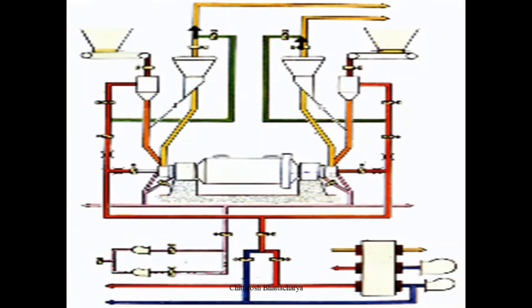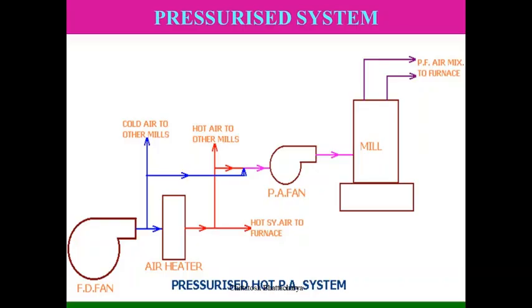We also have some bypass air supply to the classifier zone, and this air supply facilitates the classification process and helps in maintaining the pressure within the total flow line. So this way we have an arrangement of primary air supply at different zones of the tube ball mill.